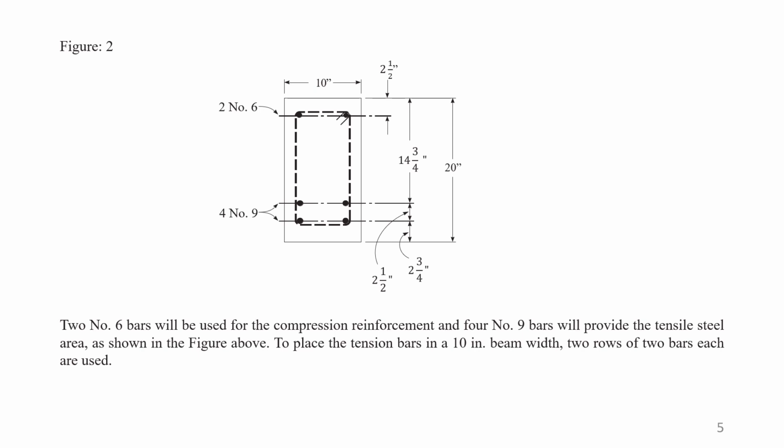This space between the bars is required for passing the aggregates between the bars while casting this beam. If there is not a sufficient gap between the bar layers, then the coarse aggregate will not pass between these two layers, only the slurry will go there, the concrete will not be strong, and its strength will not reach the standards.